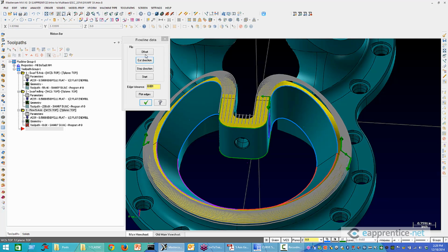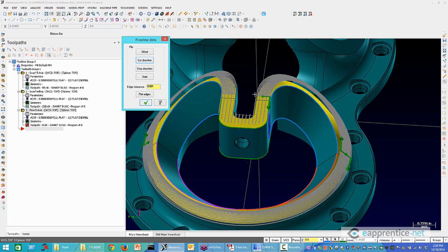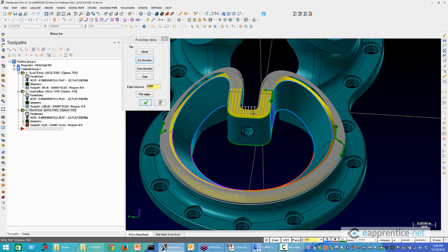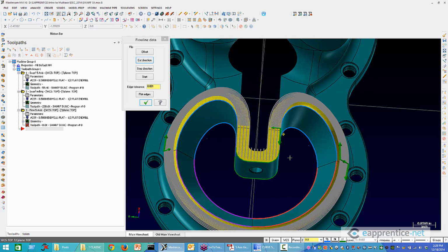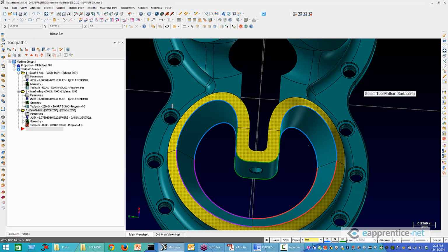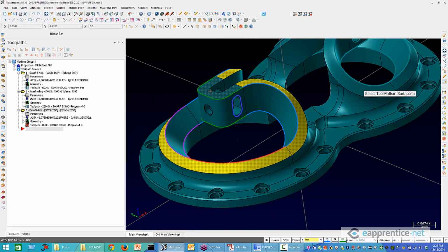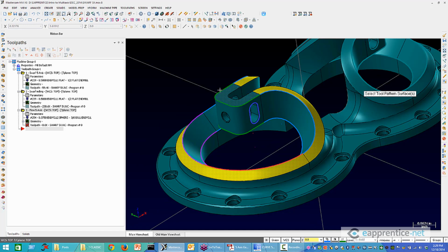Look at this surface. So if I click cut direction again, this surface was built as a square, and then the shape was trimmed. So the cut directions are not going to work if we try to flow along this way. I mean, they could maybe, depending on our stepovers and our settings, but a lot of times this will cause what's called a surface flow line conflict. For that reason, what I'm going to do is go back in my surfaces, and I'm going to deselect that top surface. That's flat anyway, so it would be silly for us to not cut that with a flat end mill.